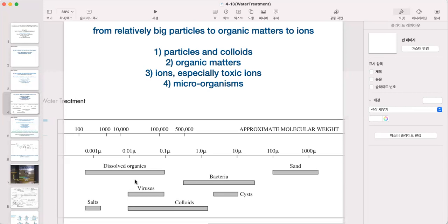Please understand, you don't have to explain this exactly. So colloid is stable, looks dirty, with the unit of turbidity, as I mentioned earlier. Why are they stable? They are negatively charged. Negatively charged colloids repel each other to stay in water forever, which we define as the stable condition.